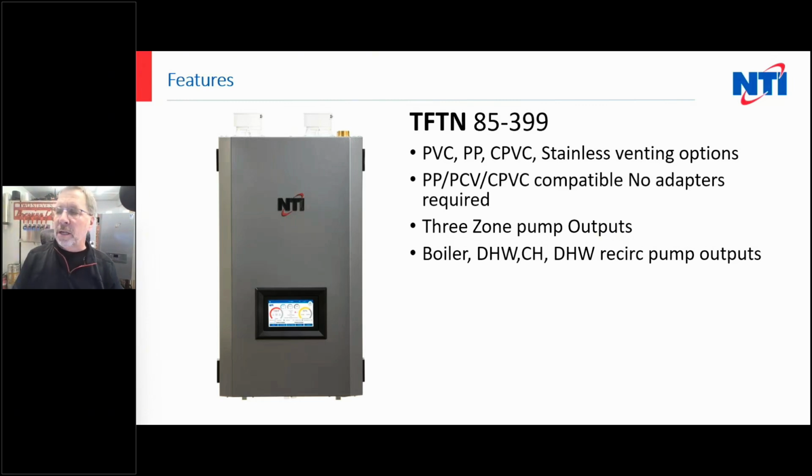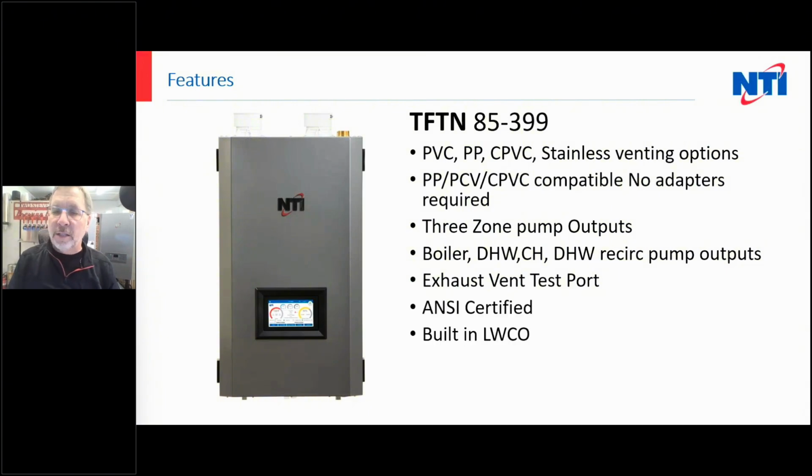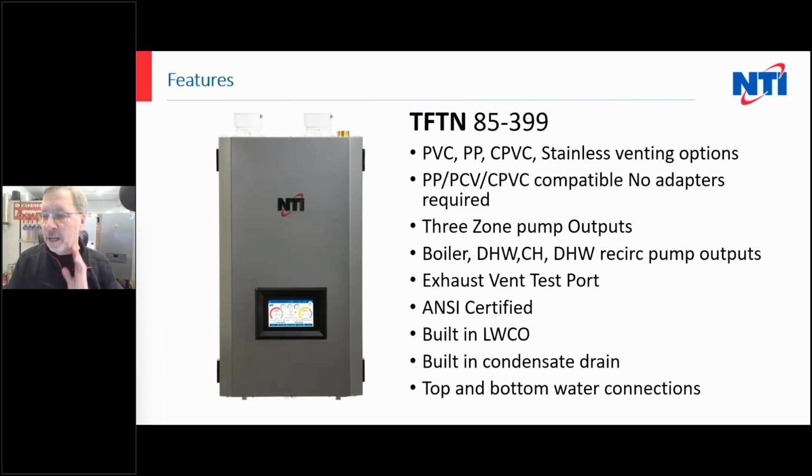Has a boiler, domestic hot water, central heat, domestic hot water recirculation pumps built in on the relays. Exhaust vent test port, of course, ANSI and ASME certified. Built-in low water cutoff, as I already said. Built-in condensate trap, and top and bottom water connections.